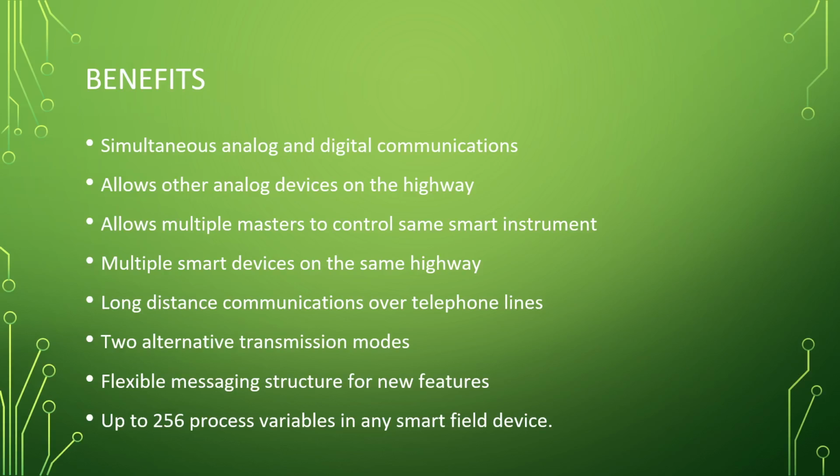Every analog input card is not HART capable. That is definitely something that you need to keep in mind. So don't be like, oh, we've got analog, we can put this HART sensor on there. Well, you probably can, but it's going to be as dumb as an analog sensor. You're going to have to configure it to only output the analog signal, or analog with the digital over it, and you're just never going to get the digital because all you have is an analog input card. So you can have an analog input with HART capabilities. That's just something to keep in the back brain there. I wonder if my analog cards are, probably not, too cheap.